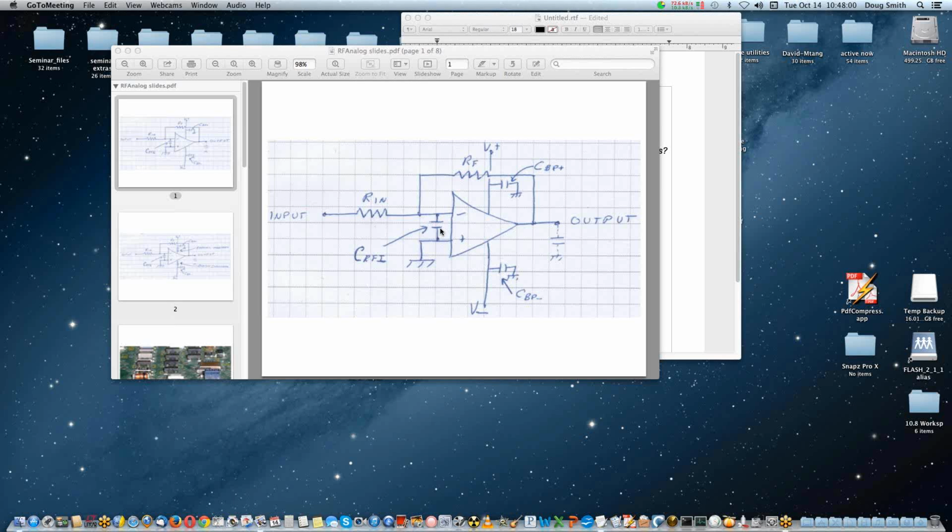The first time I encountered this, 30 years, 40 years ago, back at Bell Labs, 1980-ish, it was the logic noise generated in the board next to it in the shelf that would radiate into the fairly large loops in the analog circuits on this board. What you heard in the op amp, a voice frequency op amp that really carried human voice in a telephone system, was the software cycle running on the next board, rectified into the baseband, and that was amazing.